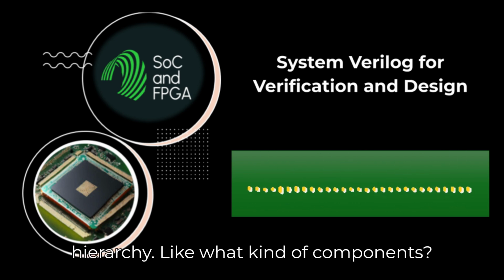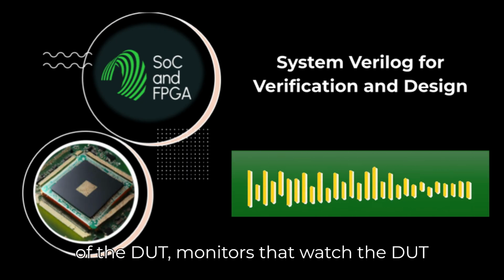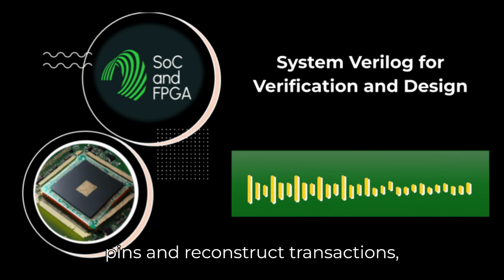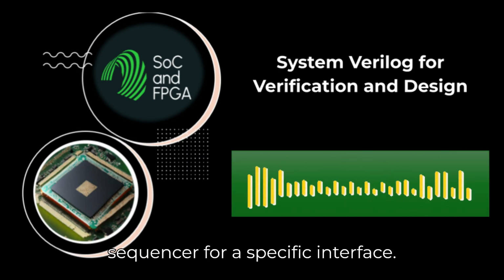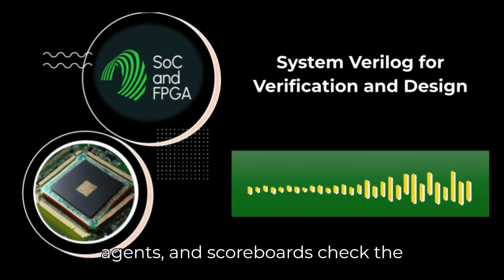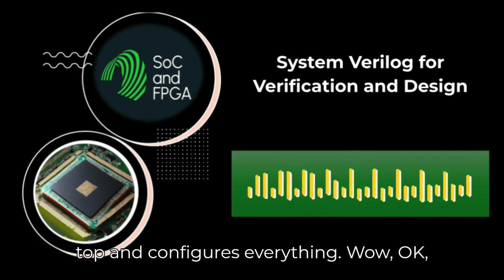Like what kind of components? Things like drivers that take transactions and wiggle the actual pins of the DUT. Monitors that watch the DUT pins and reconstruct transactions, sequencers that manage the flow of transactions to the driver. Agents usually bundle a driver, monitor, and sequencer for a specific interface. Environments contain and coordinate agents, and scoreboards check the results. The test component sits at the top and configures everything.